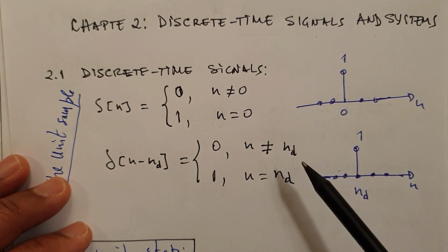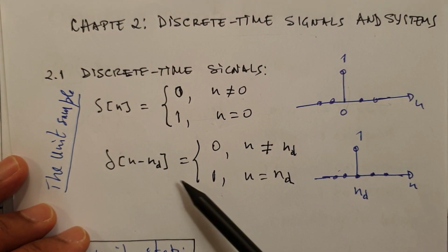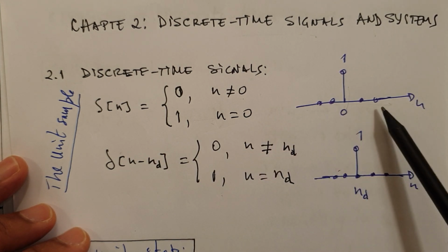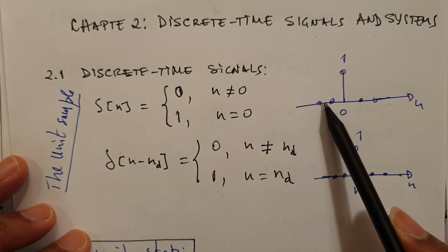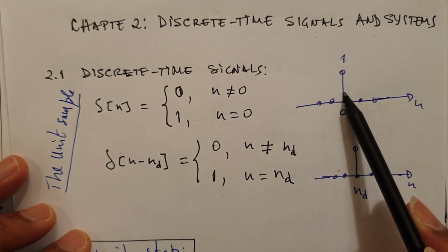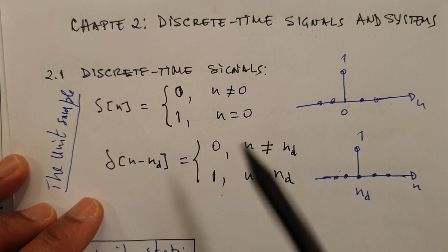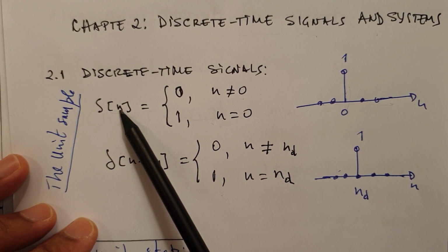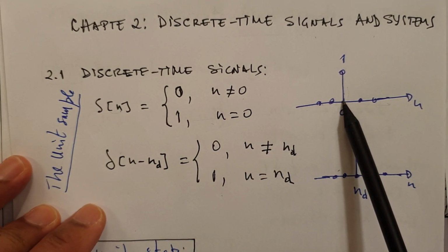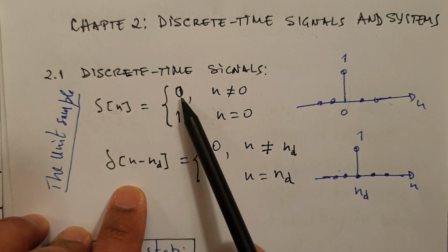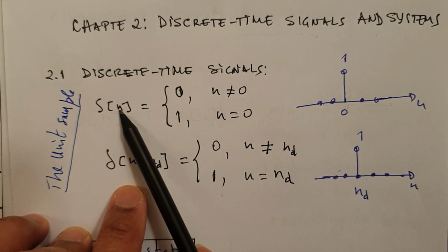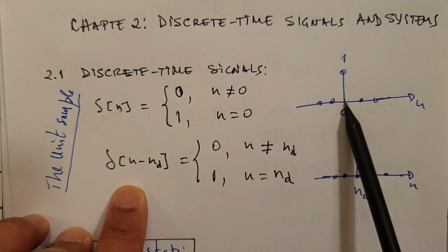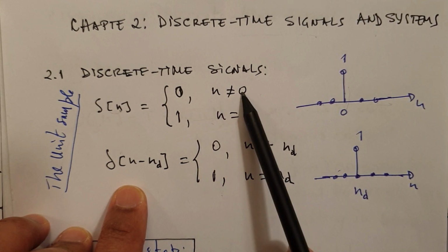Okay. So for this unit step here, the unit step then is defined as a sequence. So you have to look at this as a sequence of samples, just that in this case most samples are equal to 0 except 1. And this one sample will be located if you look at the argument of this function here. So when this argument is 0, that is where you will find this non-zero sample. Okay, for example, here we're defining that this delta, this impulse unit sample here will be 1 at n equals 0, okay, and 0 elsewhere.